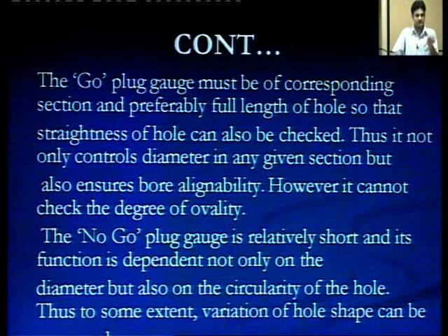So, this point should be clear: the go plug gauge should be of full length to check the straightness, and the no go plug gauge should be relatively short.